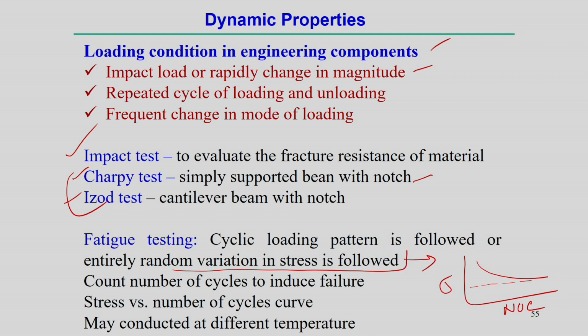Of course, this fatigue strength is less than the yield strength of a particular material, because yield strength we normally measure under static loading conditions. So, therefore, stress versus number of cycles we normally evaluate from fatigue testing. And another important parameter is the temperature at which we are conducting this test. So, at different temperatures this curve will be different.